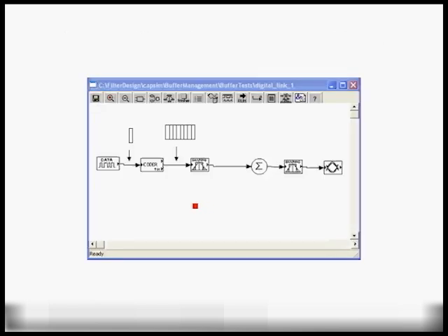In this block diagram, we show a situation where we have multi-rate signal processing. For example, in a digital communication link, the data block here generates binary data. This is the B data block. So it will generate, for example, 128 samples per visit. It can generate a gigabit, for example, but every visit it'll only generate 128 bits and put those samples or bits on its output buffer. The coder block, however, maps the bits to symbols and also increases the rate, in this case by a factor of 8.